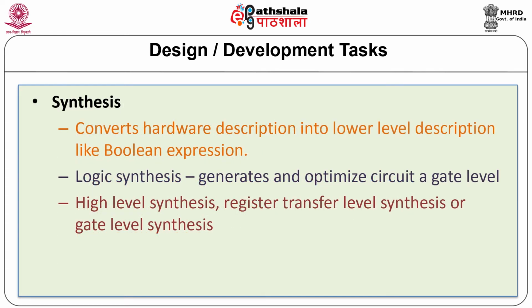Synthesis. Another design task to be performed is the synthesis. In the synthesis process, the hardware description is converted into a lower level description, for example, a logic or Boolean expression. Logic synthesis is mainly focused on generation and optimization of a circuit at logic gate level. Many available synthesis tools perform synthesis of two-level or multi-level combinational circuits and sequential circuits.